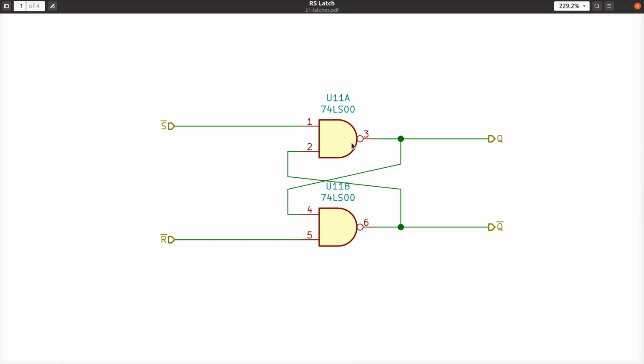So how long then does it take if the output of this gate, U11A, this little number here says it's called pin 3. This thing here is the actual name of this. You could go out and buy these gates. This is called a 74LS00. I drew this with an actual CAD tool. I'm sorry about the extra notation in here, but that's what that means if you're interested.